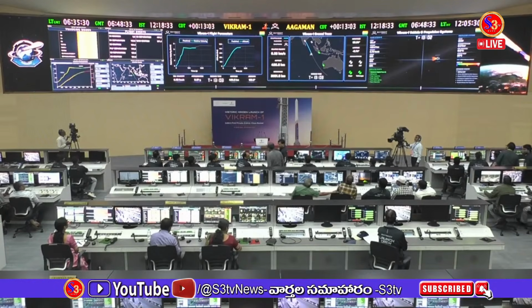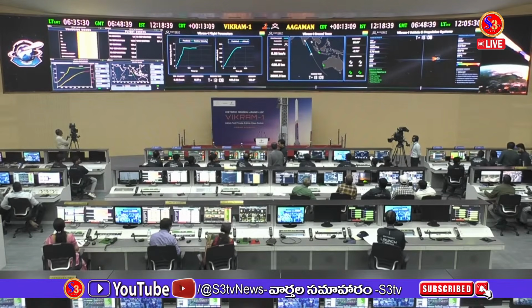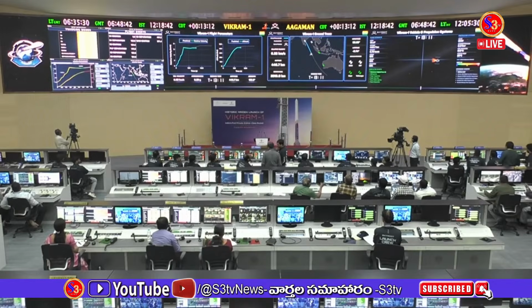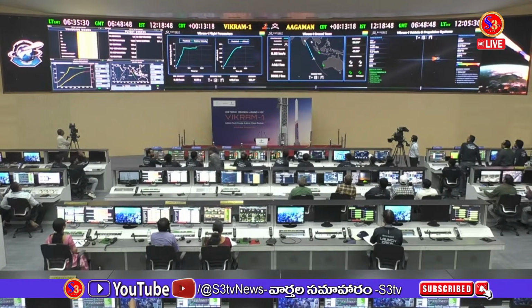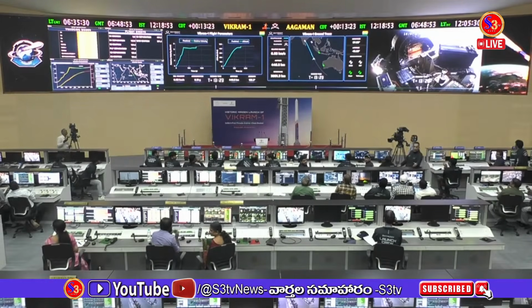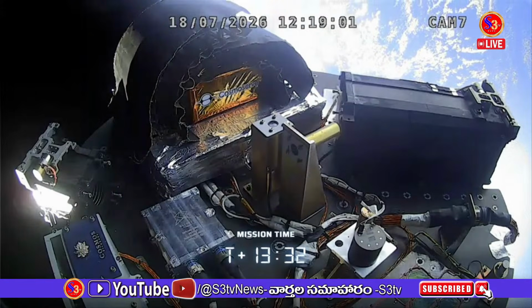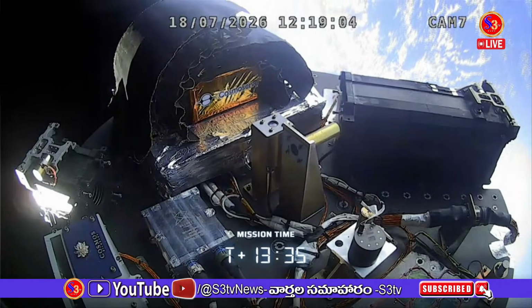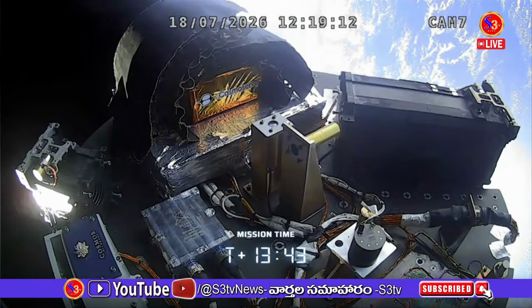So while I was talking about Raman 2 and how difficult it was to design an engine this small, the cooling design on this was exceptionally difficult to manage because the engine has to generate a lot of heat during combustion, and the temperatures can reach up to 2700 degrees. That's pretty hot for any metal or any material to sustain. In fact, many metals would just vaporize into thin air at those temperatures. So to make all of this work, we employ something known as regenerative cooling.